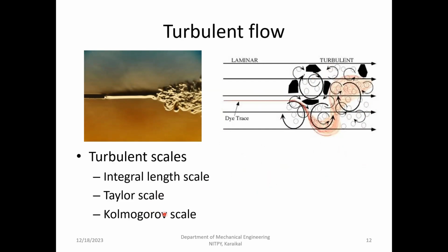Okay, so the Kolmogorov scale eddies know only two things. Either they can break further down and be dissipated as heat, or they can accumulate together and become a Taylor scale. Those small eddies don't know whether they are generated from flow inside a pipe, flow coming out of a jet, or flow over a flat plate. All they know is they can either dissipate as heat or accumulate together and form a Taylor scale. This is going to be crucial when we use the turbulent scales.